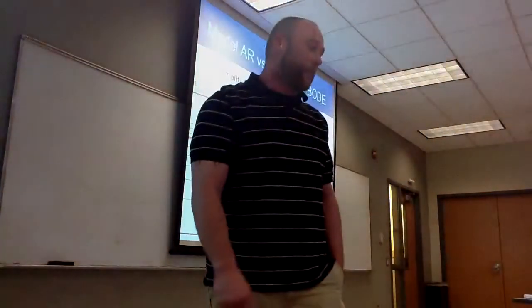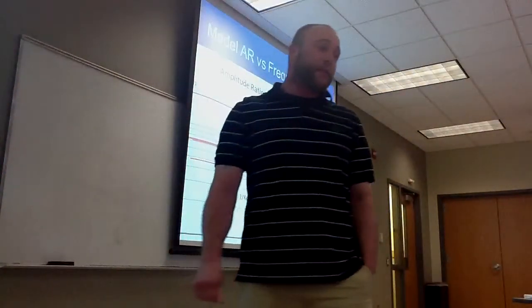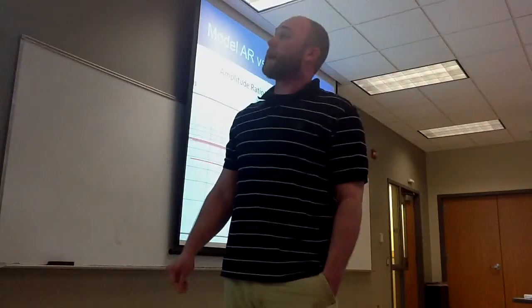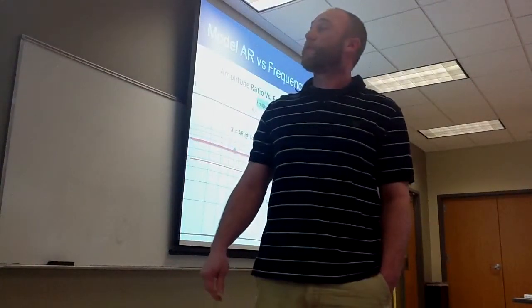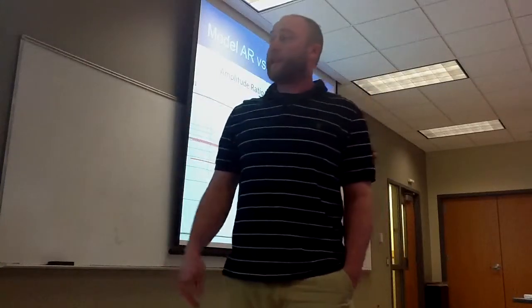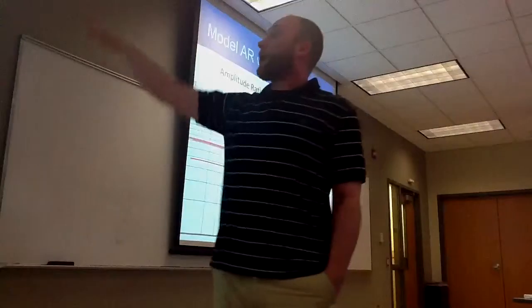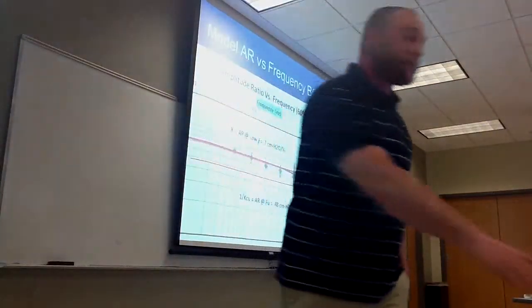Here's a model of our amplitude ratio versus our frequency from 60 to 70, where K equals 0.7 centimeters of water over percent, and our 1 over KCU is 0.48 centimeters of water over percent, where our FU came out to 2.2 hertz.